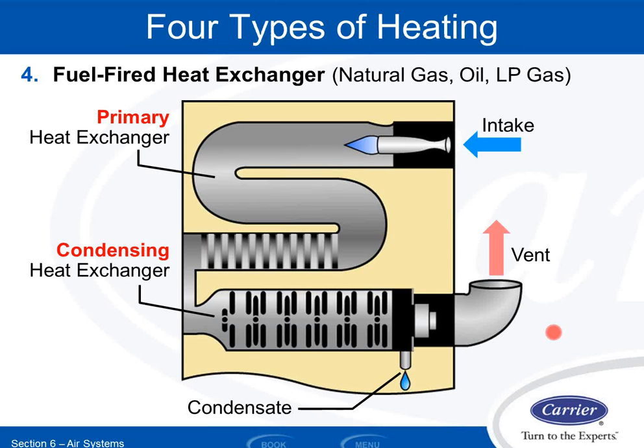So the thing is, my fuel-based heating sources, which are furnaces and the boilers themselves, typically they're around 80 to 82% efficient. If you get a condensing one like I'm showing here, you're up above 90% efficient. It's very common and affordable to get 95% furnaces and boilers, and on the market you can find 97, 98% efficient furnaces and boilers. That's about the top end.